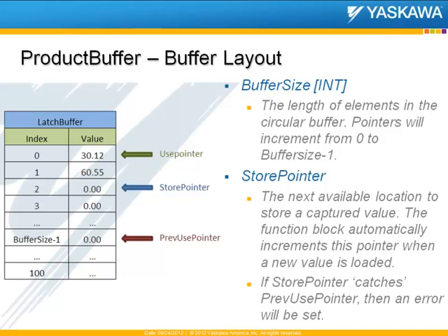And if the storage pointer ever catches up to the previous use pointer, then it will signify sort of a wraparound type condition where the elements have not been consumed as fast as they've been put in, and so that will generate an error for the block.